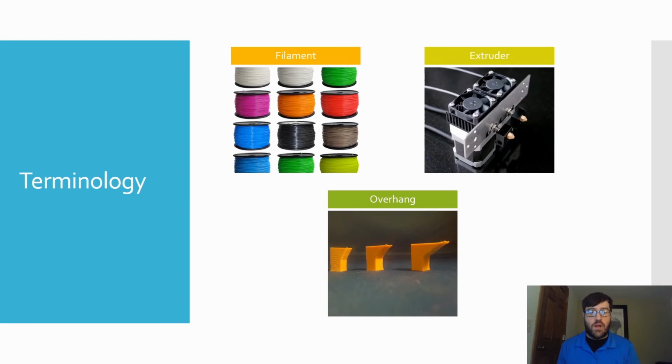And then here's that overhang we're talking about. On the left, you have a much smaller angle. You're not going to need support. In the middle, you're starting to get to it. On the right is probably as far as you'll be able to go without needing to print something underneath that angle in order to make sure that it doesn't droop or fall or not print successfully.